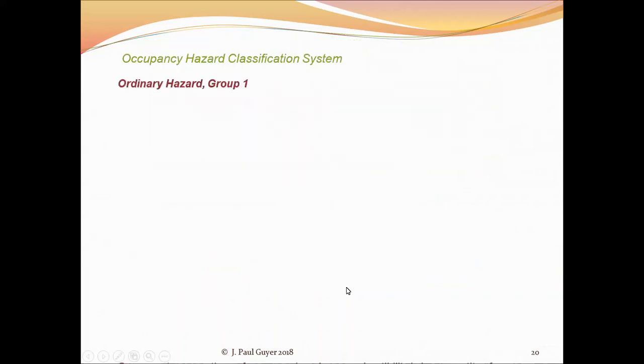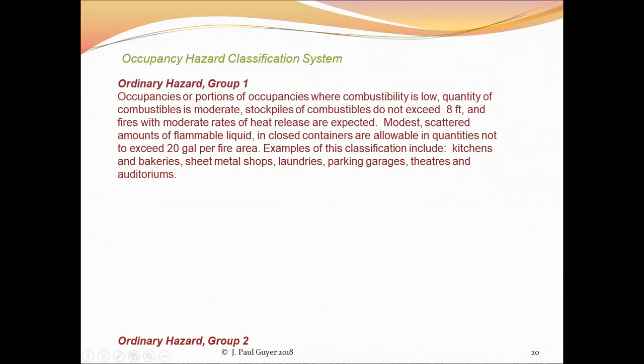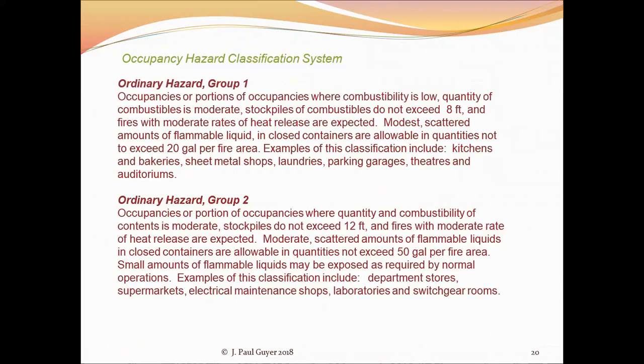Ordinary hazard group 1, more hazardous: kitchens and bakeries, sheet metal shops, laundries, parking garages, theaters, auditoriums, because you've got more hazardous activities going on in these occupancies, or the materials or stuff that's being used is more hazardous. It's flammable, that sort of thing.